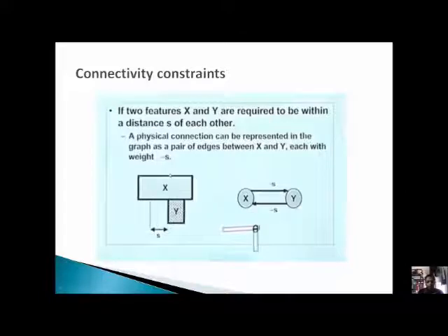That is the s we represent between the two blocks: the minimum space required to attach these two. In the layout we have seen in CAD, while connecting we have 2 lambda, 3 lambda between two metals, 2 lambda between oxide and gate.